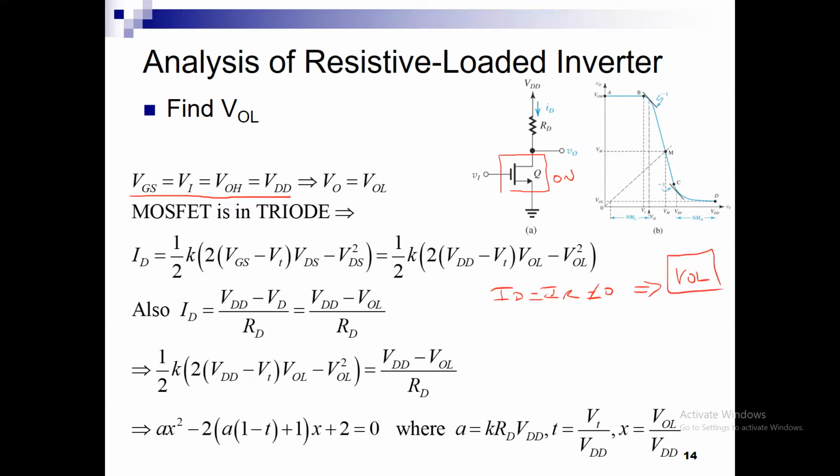So this is when the output is low. Under this scenario, we have a current flowing between VDD and ground. I know that this is on and the resistor is always a path, so there will be a path between VDD and the ground. So in this scenario, if somebody tells me VOL for this is this much, what is the current that is flowing from VDD?